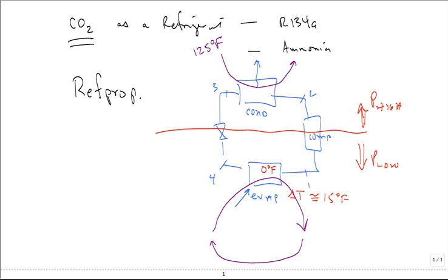And so the temperature that this condenser is going to work at, if you have a delta T of about 15 degrees F here, is the refrigerant in the condenser has to be higher. True? So it has to be what, 140 degrees F. So if your refrigerant is 140 or greater, it'll push the heat out and make the hot air outside on the roof even hotter.